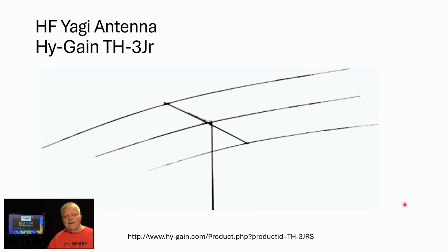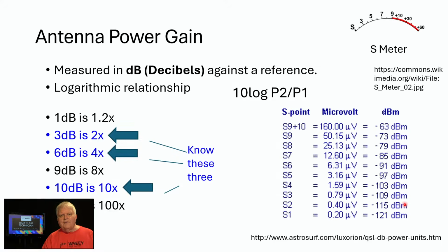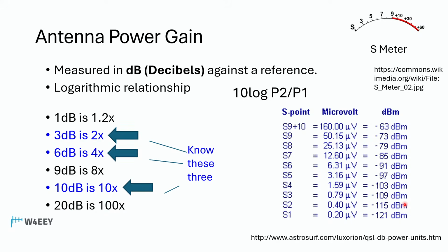And when we say that an antenna has gain, you could do math. You can say this is more microvolts than the other, but we use decibels. Decibels is actually easier when you're making reference to a standard. And that standard could be the dipole antenna, or it could be the isotropic antenna. And these are the ones that I want you to know about.